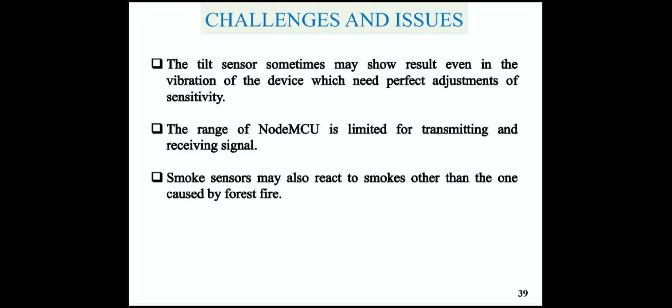The challenges that we faced during our project are that the tilt sensor may sometimes show a result even with the vibration of the device, which needs perfect adjustment of sensitivity. The range of the NodeMCU is limited for transmitting and receiving signals, and the smoke sensor may also react to smoke other than that caused by a forest fire.